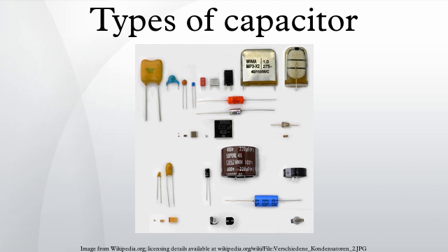Capacitance ranges from picofarad to more than hundreds of farad. Voltage ratings can reach 100 kV. In general, capacitance and voltage correlate with physical size and cost. Miniaturization. As in other areas of electronics, volumetric efficiency measures the performance of electronic function per unit volume. For capacitors, the volumetric efficiency is measured with the CV product, calculated by multiplying the capacitance by the maximum voltage rating, divided by the volume. From 1970 to 2005, volumetric efficiencies have improved dramatically.